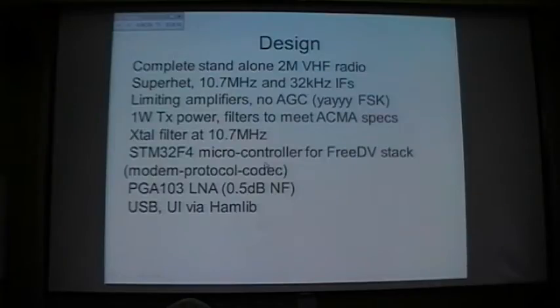It's got a bunch of limiting amplifiers in the transmit receive chain, no AGC. I really like FSK. It's the first time I've really worked with FSK. I'm used to radios and modems that need linear modulation, like phase shift keying and analog, and they're very sensitive to distortions in the amplifier chains. FSK, you can bash it around a bunch of different ways, and we still get really good quality and really good performance out of it. So becoming a bit of a fan.